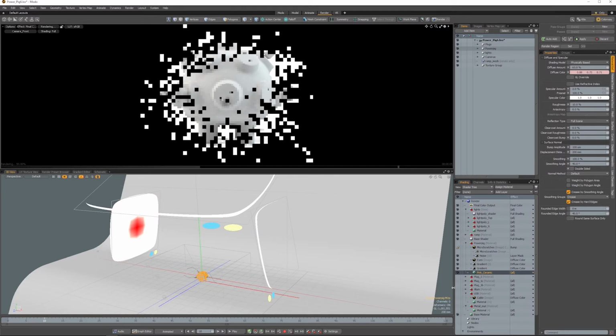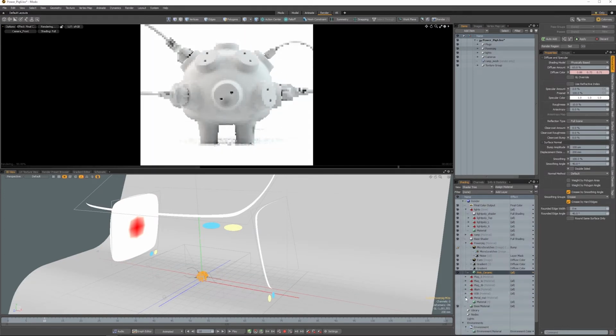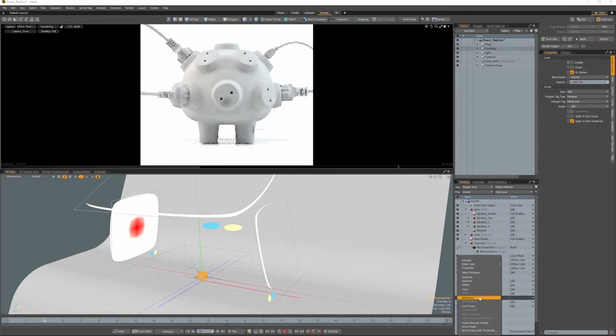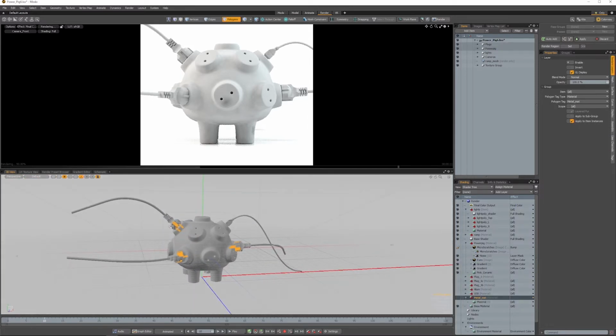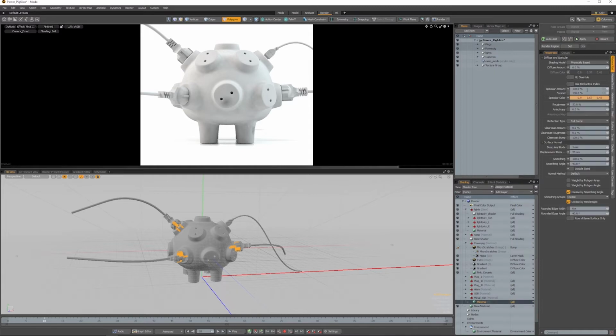Alright, so starting maybe from the bottom, let's go to the metal matte. If you select the polygons, you'll see that those are the metallic parts of the plug. So those are only visible here on this specific angle. So I just made the specular material with kind of orange color. So you'll see it will show up there. I'll have to activate it.